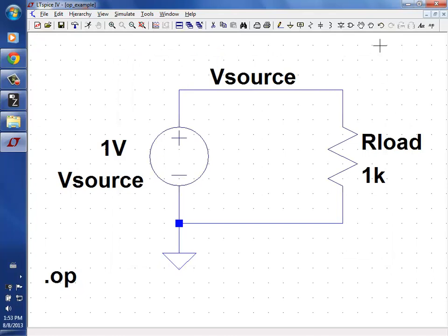That shouldn't confuse you, and you should remember this, because if you don't, you'll be confused when you're trying to verify your homework solutions with SPICE. When you're learning, if you simulate your homework first and you know what the answers are, then you can verify your hand calculations. But SPICE defines positive current flow as from plus to minus. So even though the current, or water, is flowing like this, SPICE defines a positive current through a voltage source as from plus to minus.